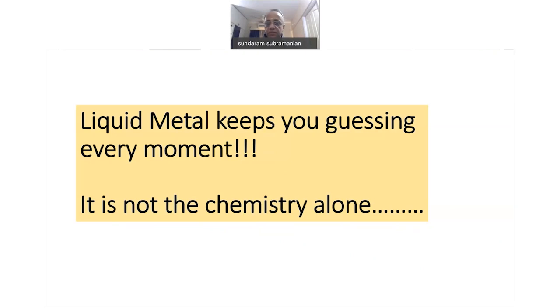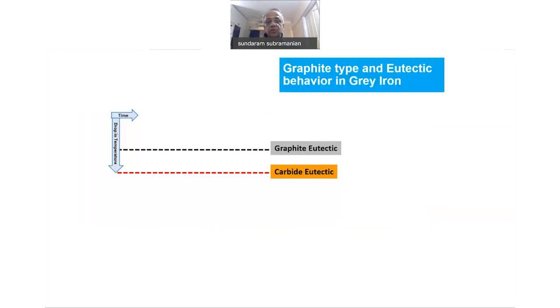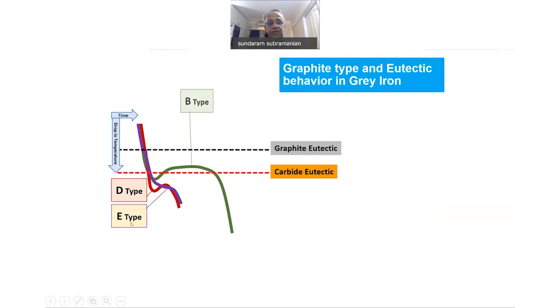Some example, let us see. One is about graphitization. Inside the mold, when the metal is cooling, there is solidification taking place. During the solidification process, we precipitate graphite in a controlled way. Now, here are some examples of uncontrolled ways in which graphite can precipitate. E-type and D-type graphites, they produce carbide and unwanted graphite structures. The B-type is equally bad because some of this is undercooled.